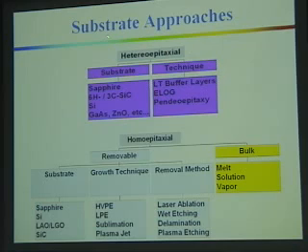Most of the attempts that we've been doing to date, the ones that got us to this point, have been the heteroepitaxy growth. And in particular, we've used sapphire plus silicon carbide, and to a much lesser extent, these substrates. These have been relatively unsuccessful to date. We've done it by using a low temperature buffer layer to allow us to have a layer in between the substrate and the gallium nitride to serve as a nucleating grain growth area to allow single crystal gallium nitride to be grown at large mismatch, but with large dislocation density.